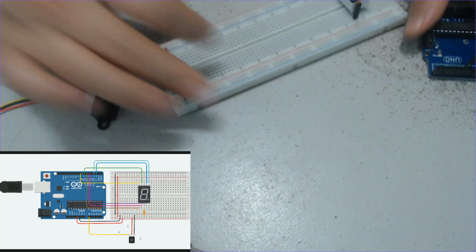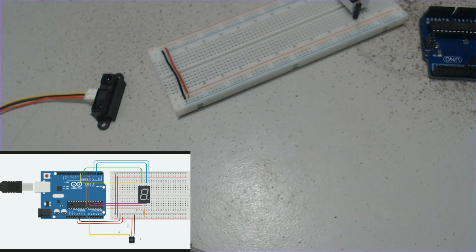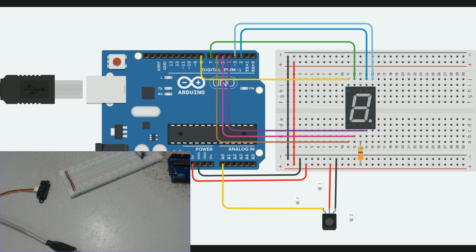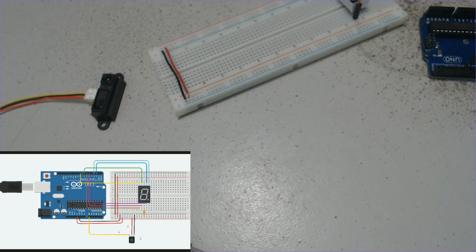So if we go back to my diagram, we identify port numbers, port number 5, it's connected to port number 2 on the 7-segment display. So I'm going to use purple also. I got purple, fortunately. Here it is, my purple. Let's go back. Remember, 5 to port 2. 5 from the Arduino to port number 2 on the 7-segment display.